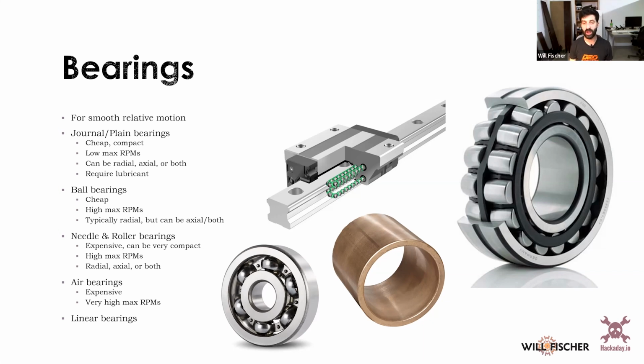Air bearings are where you have a gap between two very precisely made materials and you pipe air into it. And then that air prevents things from touching. And you can get extremely high max RPMs, like hundreds of thousands of RPMs. But they tend to be really expensive because the manufacturing tolerances are so tight.